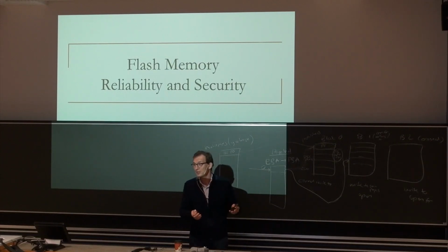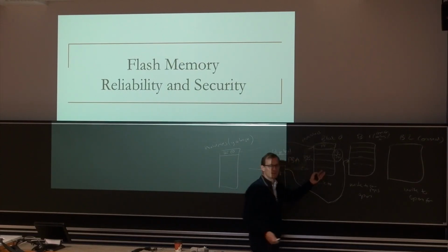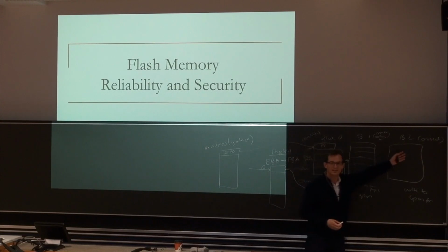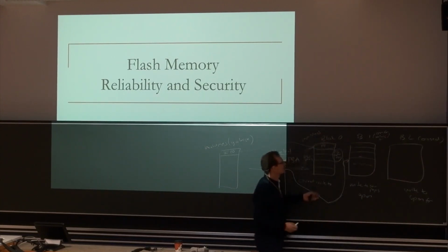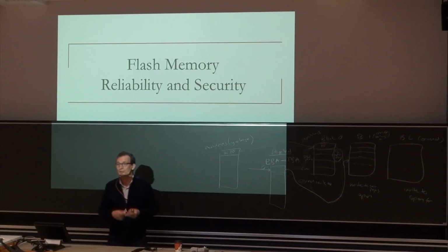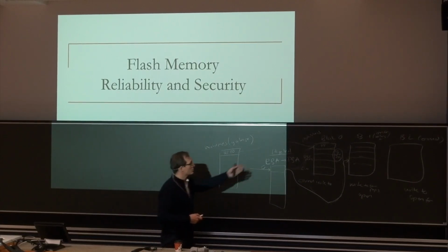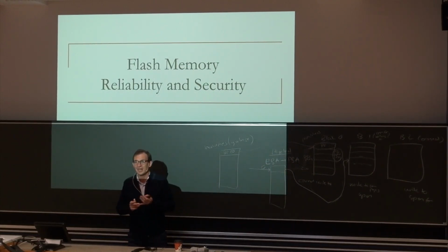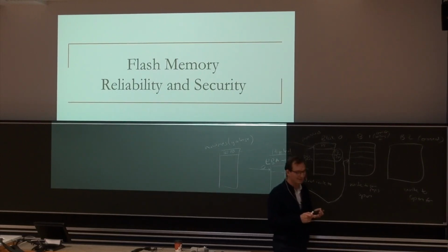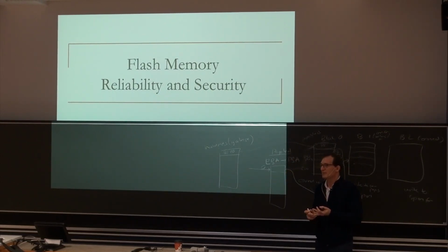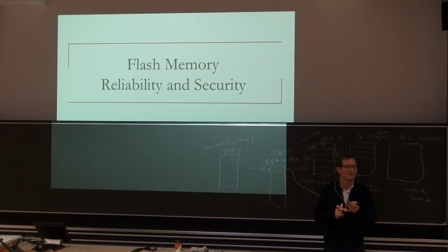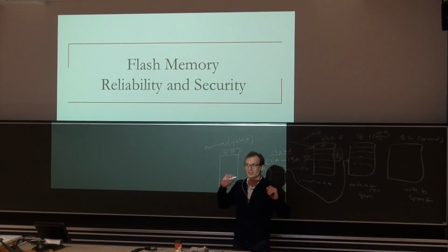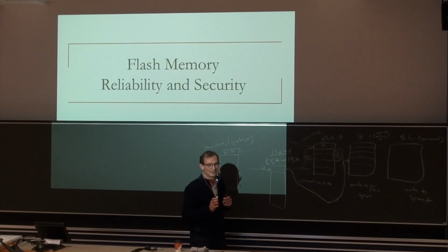But you can be proactive also. You can say, oh, I'm wasting most of my space in this block, so I'm going to declare this as mostly garbage, and I'm going to move the useful stuff to some other block, and then I'm going to erase it such that somebody else can use it. So controllers are doing this in the background all the time to ensure that they have enough space over here. And this is happening because the read granularity is at the page level, and the erase and program granularity is at the block level. And the block level is huge.